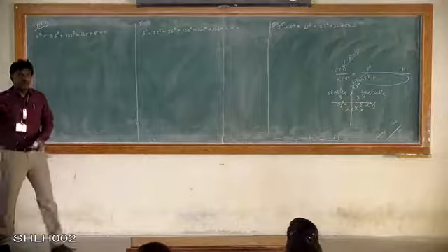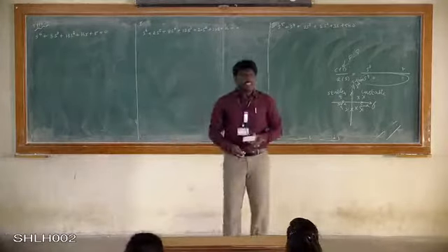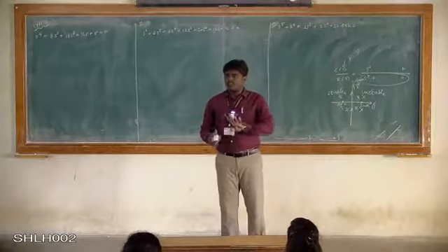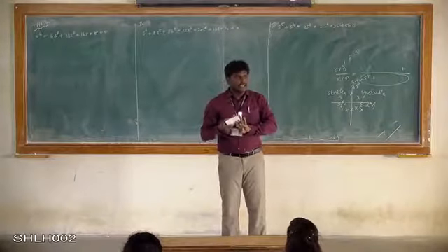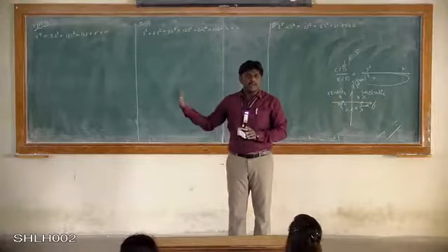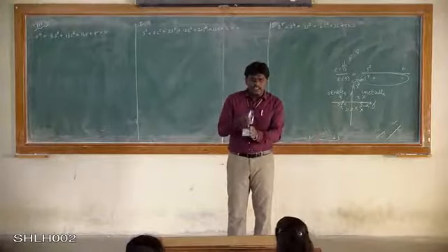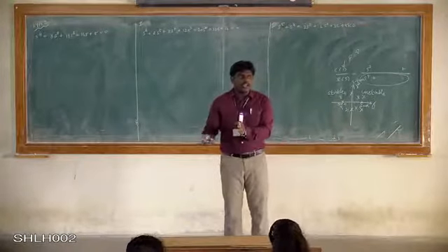Right. So what is the order of the system? It is S power 4. So that means 4 roots will be there. Using the Routh table, we will have to make the Routh table, and we will have to say how many poles will be on the left side and how many poles will be on the right side, right?